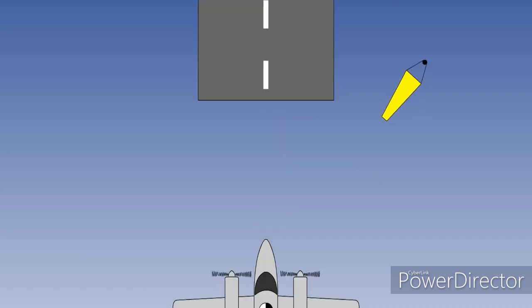The second use of the rudder we will look at is takeoff or landing with a crosswind. The landing approach is illustrated with a right crosswind. If you position the aircraft on the extended runway centerline with a right crosswind, the aircraft will drift to the left.